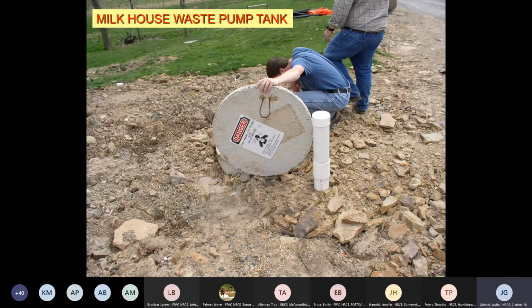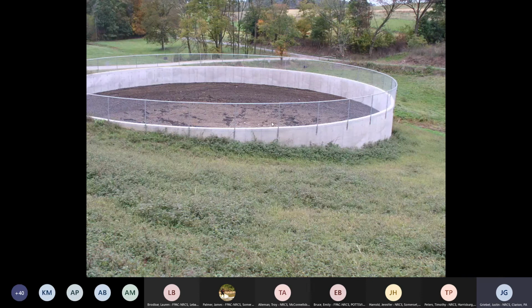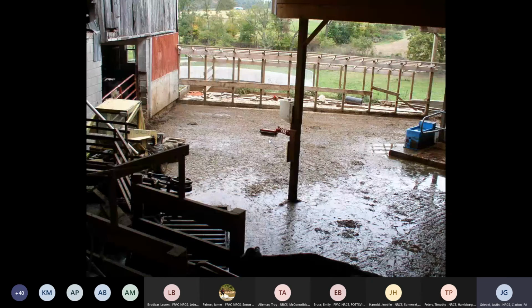There's a large tank that we contain it in. If we don't have a manure storage tank on that farm, we can dilute the water and put it out to a spray irrigation system or a manifold system to treat that water over a vegetated strip. But here you can see we installed a large manure tank with a conveyor system to transfer the manure from up above where the heavy use area is down to the tank. There's another view of the tank, everything collected inside.